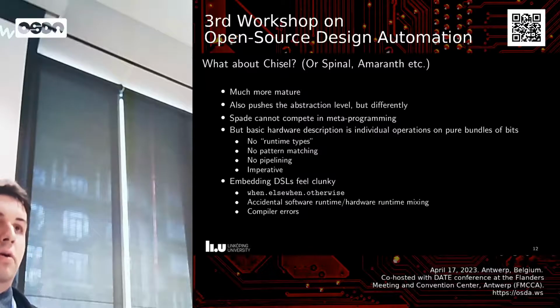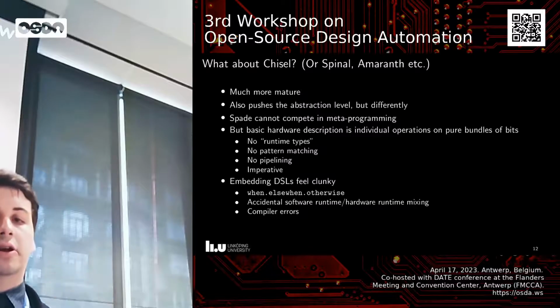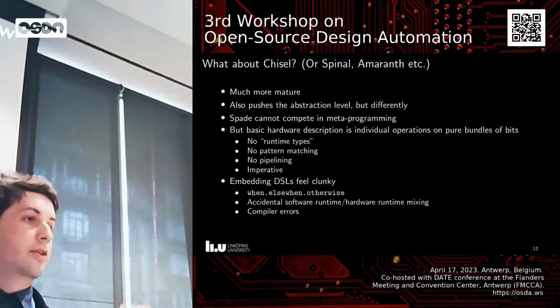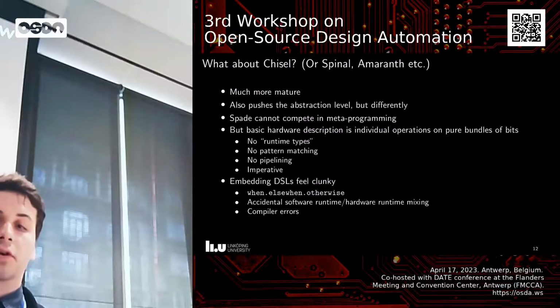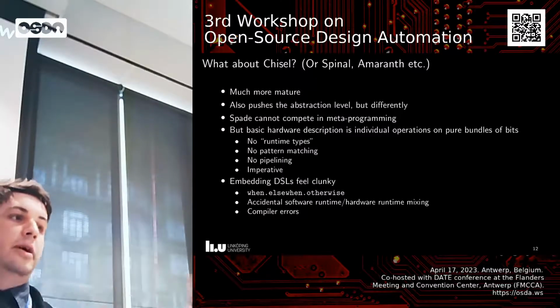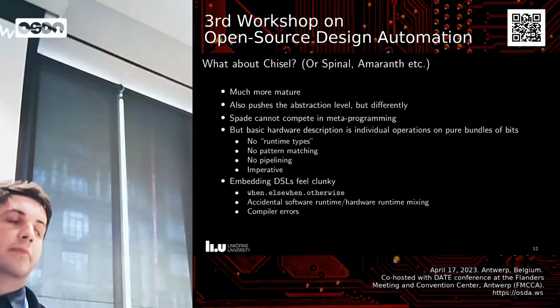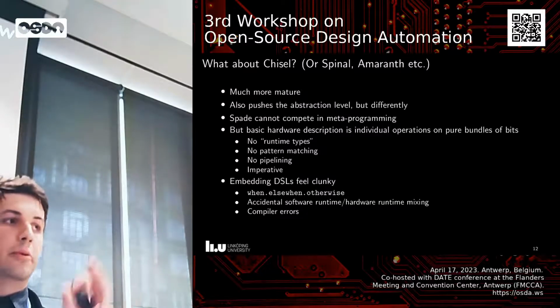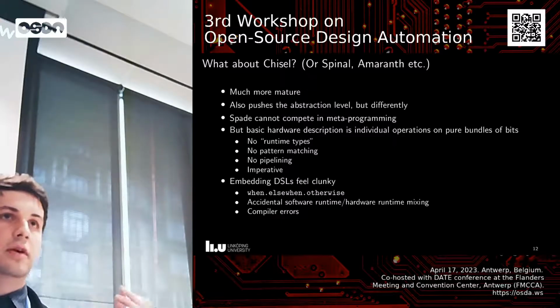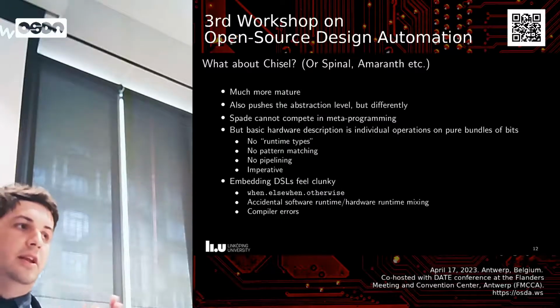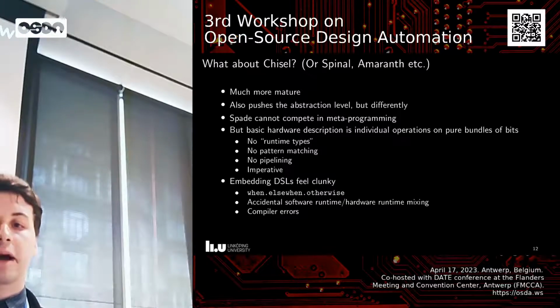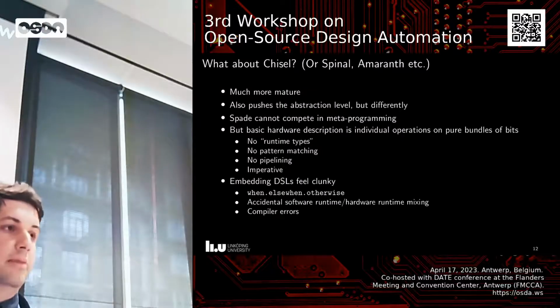I would say all of the languages kind of push the abstraction level, but Chisel in particular, and I guess all the other sort of hardware construction languages, as I think they call them, do so by doing metaprogramming. But when you can't use metaprogramming, when you're describing the individual operations that you want to perform, you're still doing bundles of bits and individual operations on those bundles of bits. So there's no pipelining feature because it's just bundles of bits. You don't have any nice types at the hardware level. You don't have this pattern matching that you can do on the enums.